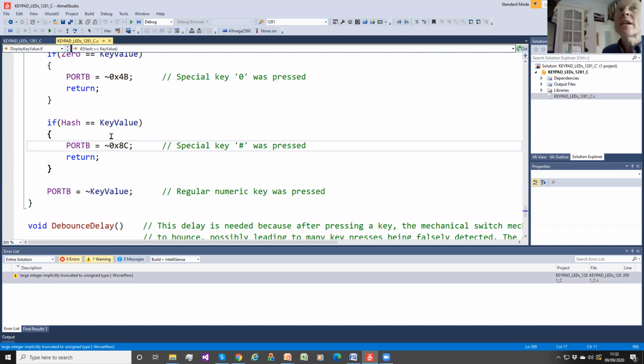And when I take this number, that doesn't cause a problem on its own. But when I take a constant number like this, and this is just to show a different pattern on the LED, so it's a fixed value, and I put that into a port, this is only 8 bits. This is a 16-bit number. And I'm putting a 16-bit number in an 8-bit port. Now, in this particular case, it doesn't matter, because I knew that when I wrote the code, and I only used an 8-bit value. But supposing I'd put 38C, it's a much bigger number. That is only 8 bits here. So I'm going to lose some of my data.